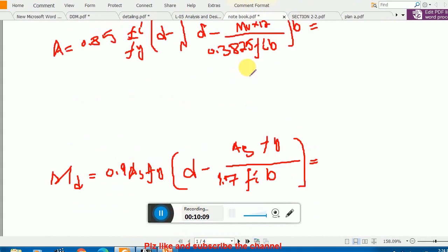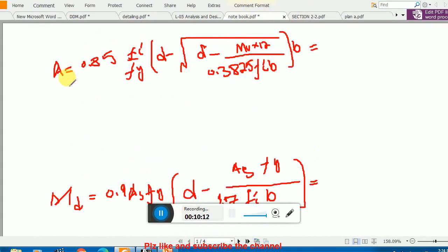Okay, how you will check? We will use this formula. Number 5 at the rate of 6 inch will give me an AST. Remember, it will give me an AST from the spacing formula. Number 5 area is 0.31 divided by 6 times 12. It will give you how much amount of steel. Please take up your calculator.